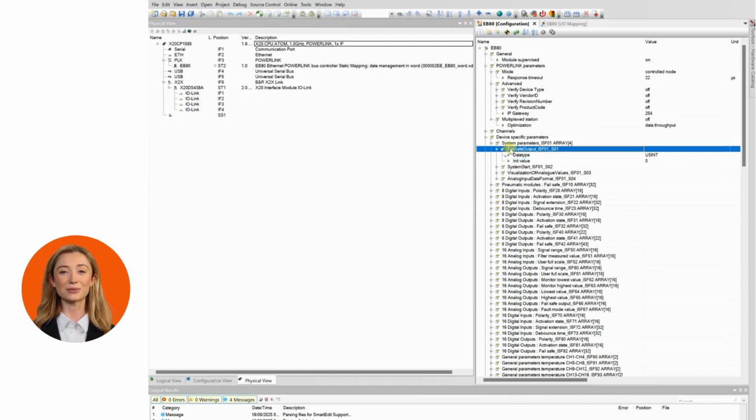There are 3 different modes available for the pneumatic module. Output reset default. All solenoid valves are deactivated. Hold last state. All solenoid valves maintain the state they were in before communication with the master was interrupted. Output fault mode. It is possible to select the behavior of each individual pilot, which can be set to 3 modes in the pneumatic module's fail-safe field.